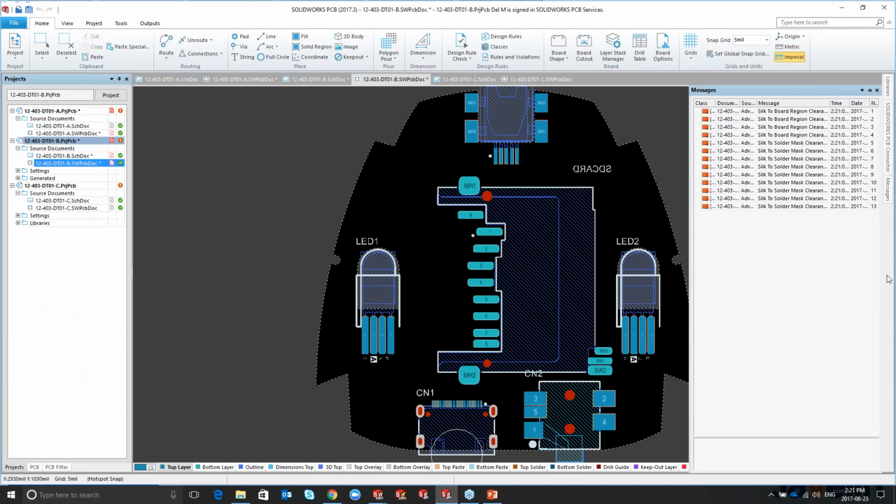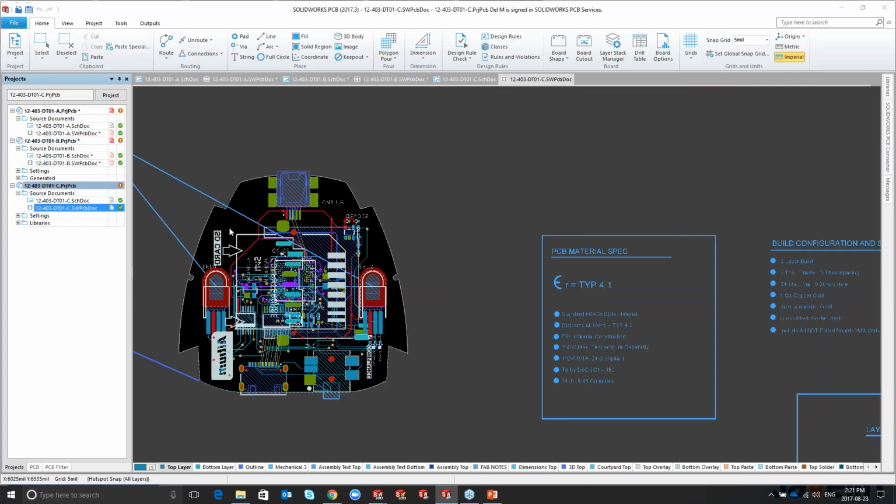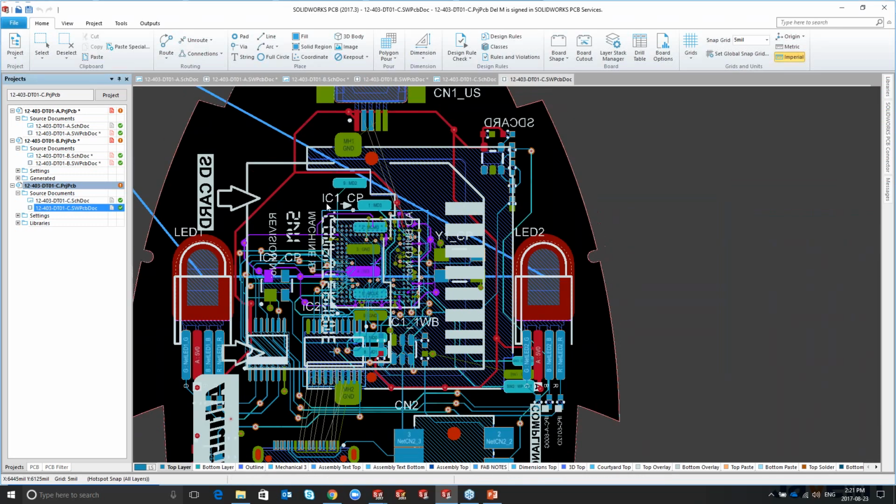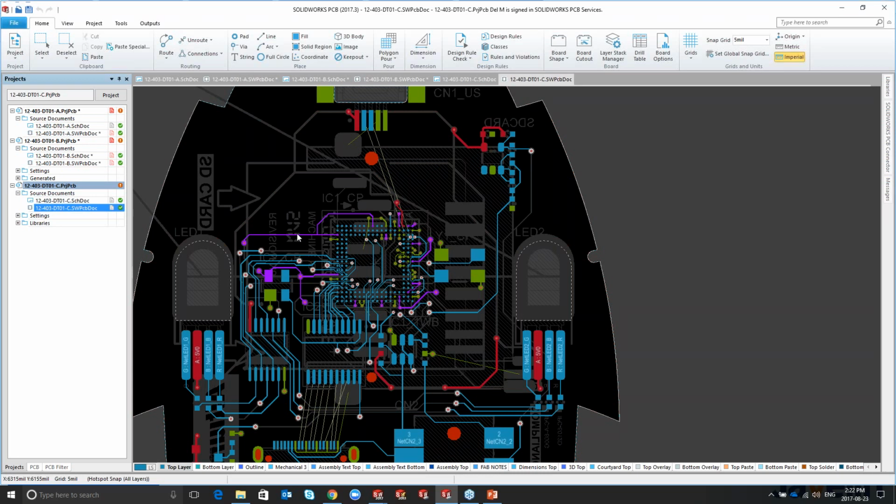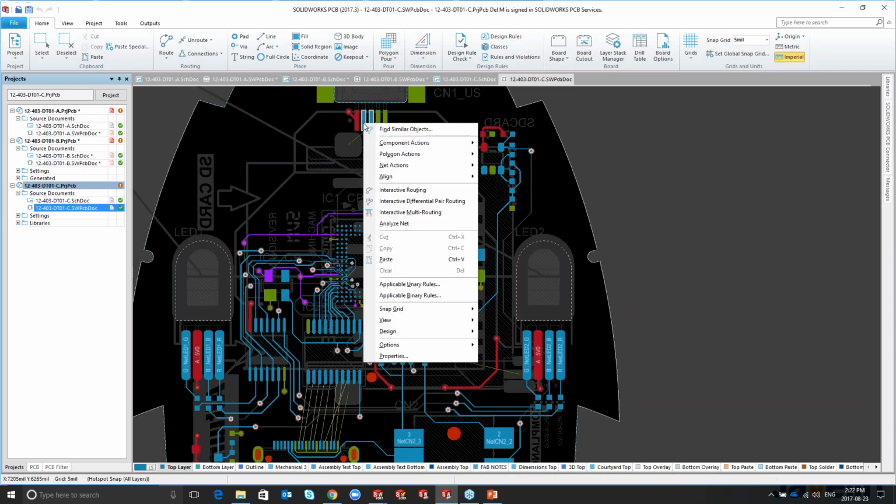Alright, so with that, I'm going to start taking a look at the last part of it, where I want to talk about routing. So in here I have already placed some of my information, and we've placed some of the components. We've started off the routing. I'm going to simply turn off all the layers, so I have a single layer by using shortcuts like Shift S.